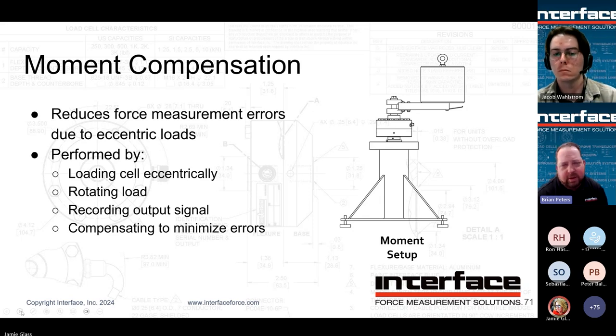And that is that we will go in and actually adjust the load cell as necessary to ensure that it meets a certain spec when subjected to a pretty terrible off-axis load. So as depicted here, there's an LP bolted down to a base. If it's an 1100 or a 1600, that's going to be a base it ships with, for example. Otherwise, it would be a representative base that gets bolted down. This is before we put the diaphragm covers in, so the gauge cavity is exposed.